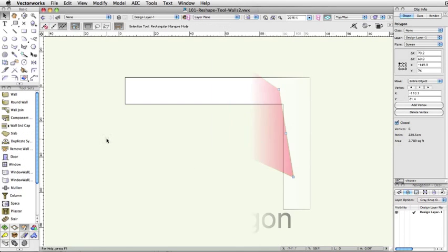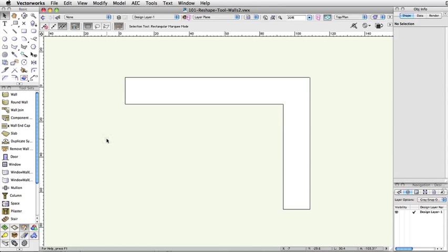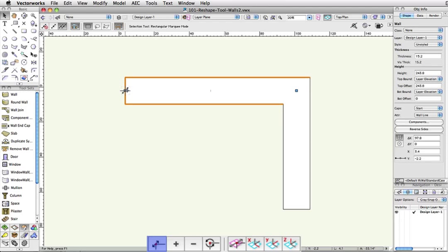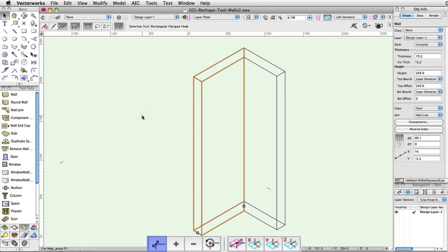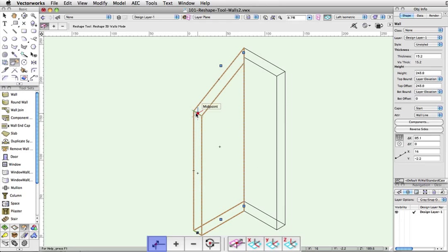With a 3D object selected, such as a wall or 3D polygon, you'll see these modes. Move Vertex allows you to manipulate one vertex. In top plan view, you'll only be able to move an object along the X and Y axis. If you want to move one of these vertices in the Z-axis, you would change to another view, such as front or side. Holding Shift down while moving this vertex lets you lock to a particular axis for easier editing.